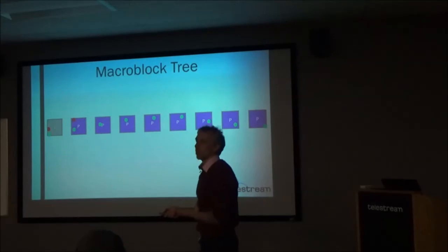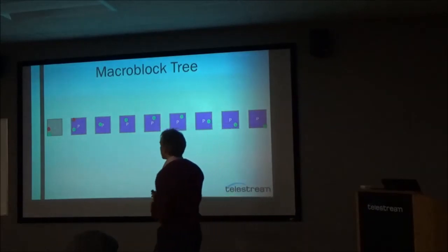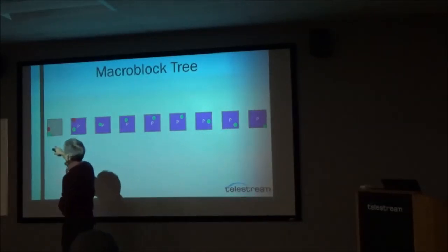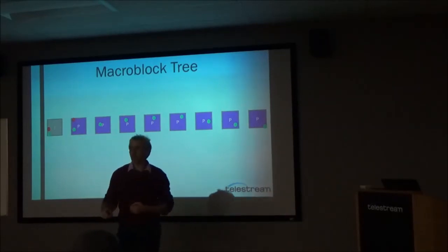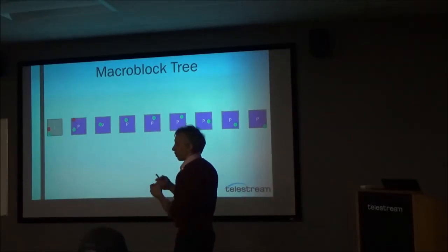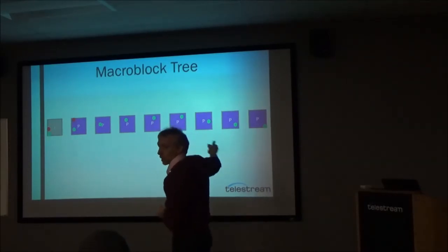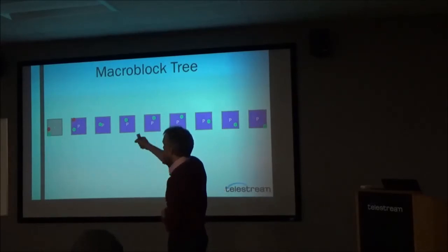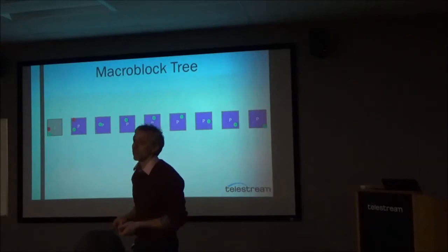And so when I'm trying to work out my quantization values or how many bits I want to invest, I'm going to invest a lot more in the pixels in the green ball than in the pixels in the red ball. I'm going to represent that green ball a lot more accurately because I get to reuse that investment all the way down the line. Whereas any investment I put in the red ball, that's gone. It's fleeting. Probably nobody would even notice.